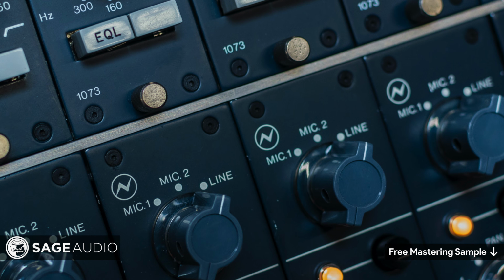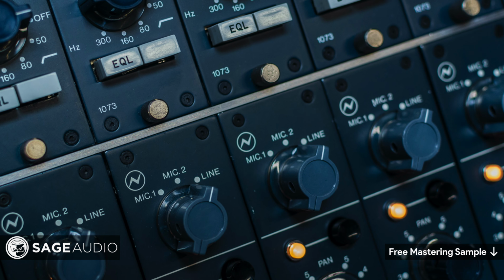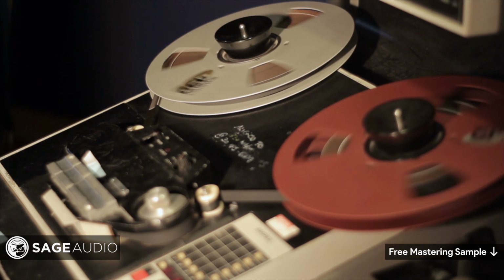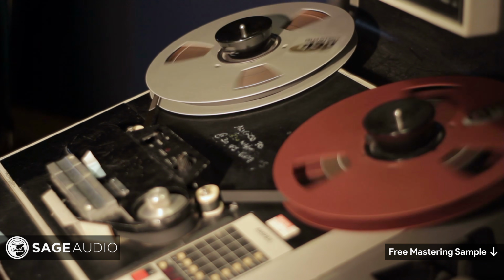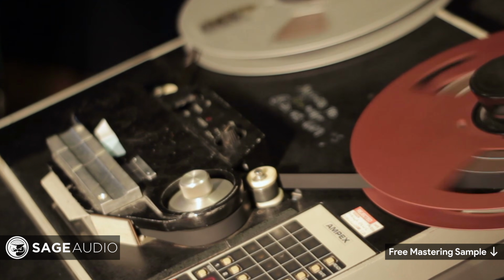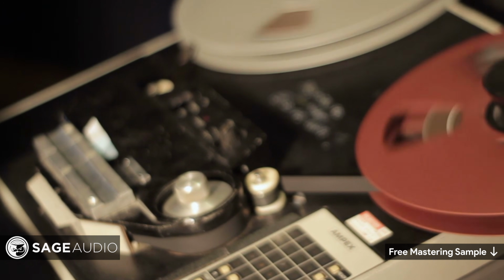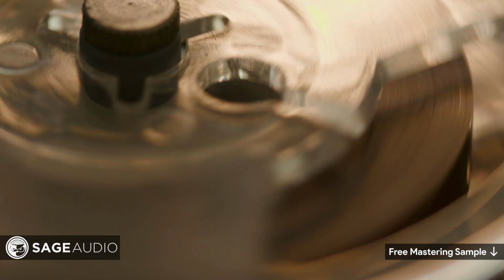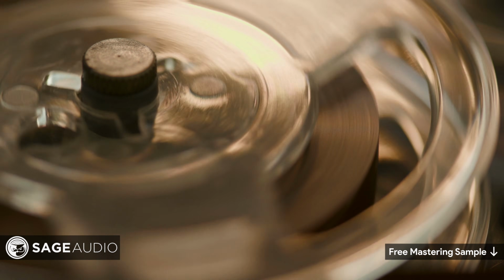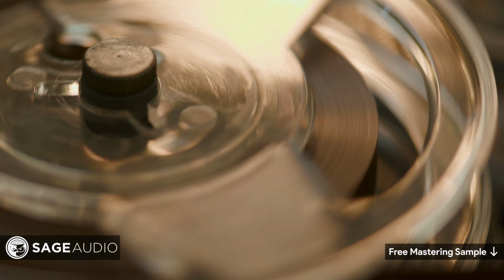Next, let's look at what tape, tube, and transistor or transformer saturation looks like. Tape saturation occurs when the magnetic particles embedded in the tape can no longer be rearranged or have their poles reoriented. This happens when a loud enough signal is recorded that requires the entirety or majority of these magnetic particles. If there are no more particles that can be reoriented, compression and harmonic generation will begin to occur. This will often result in both even and odd harmonic generation.